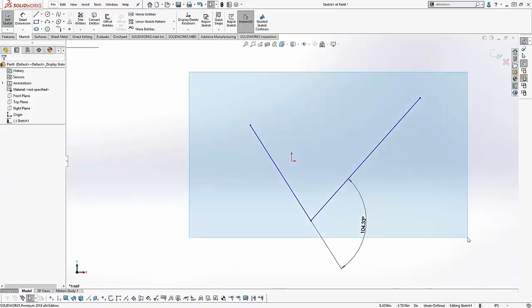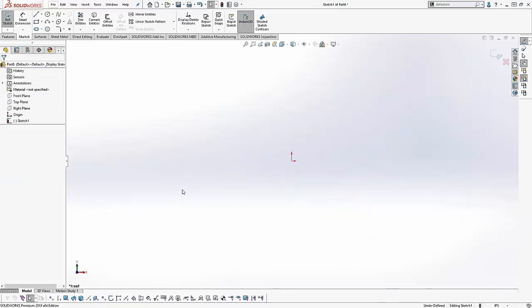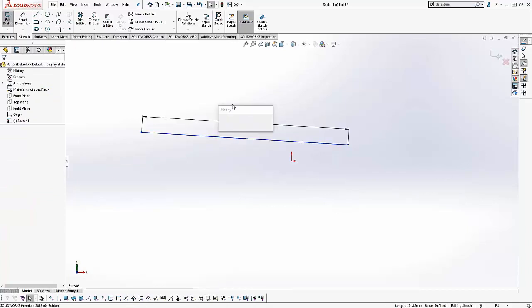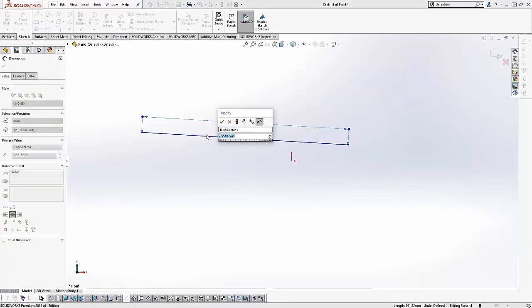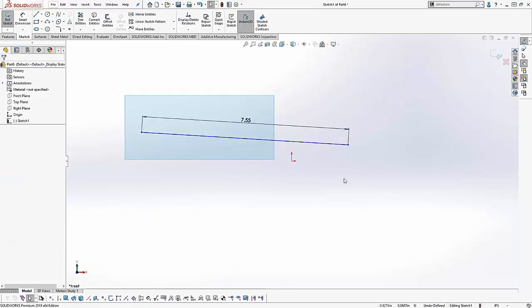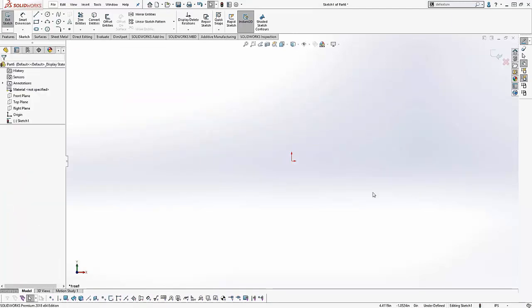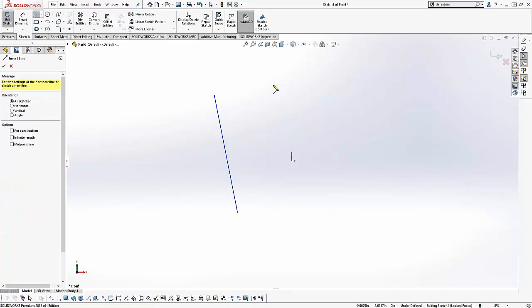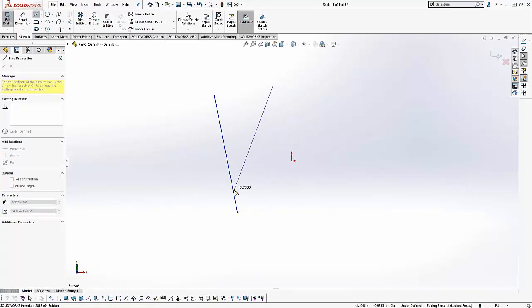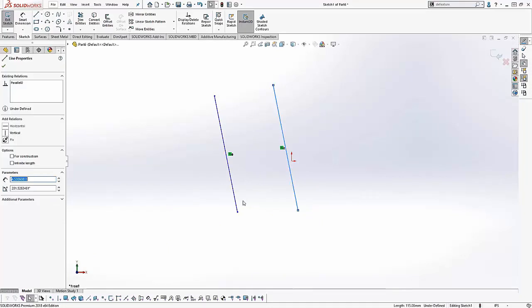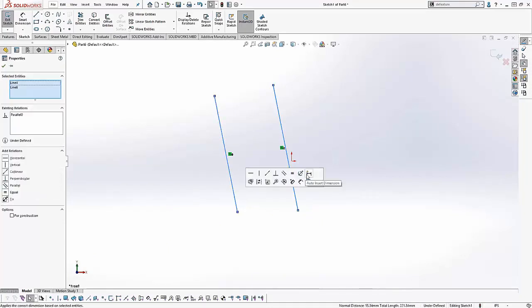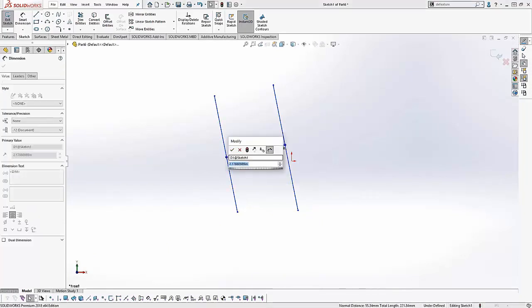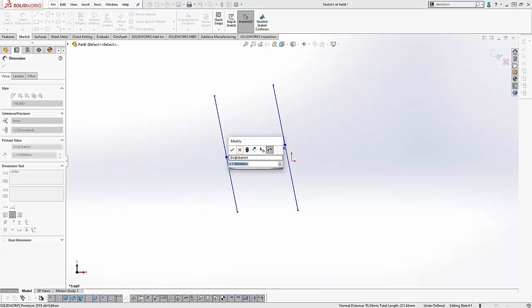This can also be done for singular straight lines, auto dimensioning just the linear distance of that line, or doing two parallel lines. So there's a number of different pre-configured options. So let's go ahead and grab this component, make it parallel, pre-select between the two of them, and you now have the ability to auto-insert the dimension and just do the distance between the two parallel lines.